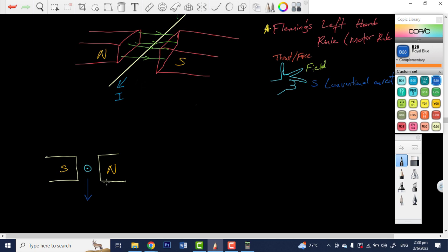So they will oftentimes give you diagrams like this. They might give you one like this now. So same idea. So south right here, north. But in this case now we have a conductor carrying the current into the page. So the current is going into the page. So we line up our fingers, index from right to left, middle finger into the page. So your thumb points upward, so the force will be upward. So this is the force right here, that's the force right here.